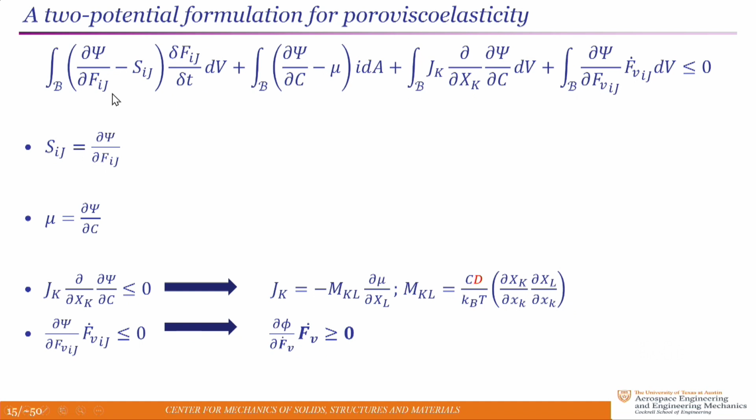Okay, any other questions? This is more of a curiosity. Going back to the cracking experiments, you had rather large dissipation energies, right? So that's ductile fracture? No, it is not. There's no notion of plasticity. There are inelastic strains that are part of the viscous branch. Okay, that's what I wanted to know. Thank you.